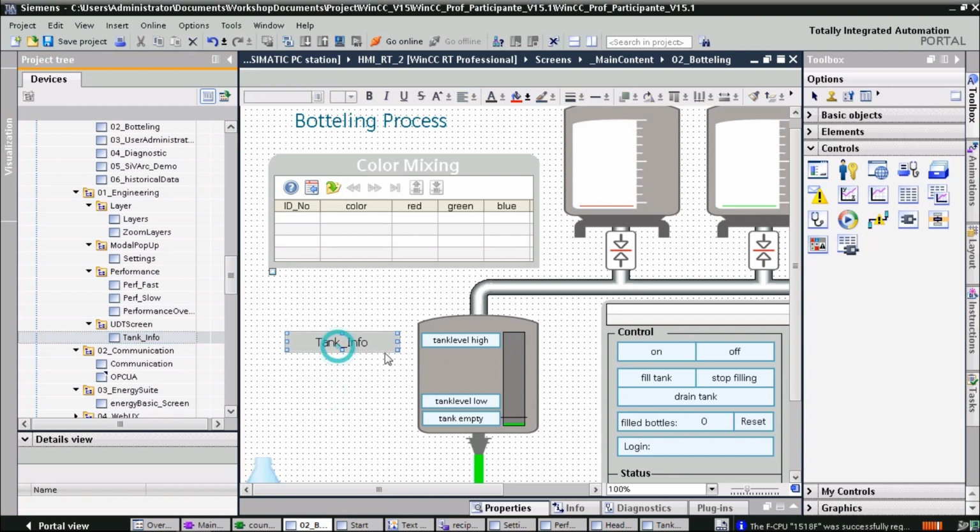So in the case of the red tag, we switch to our UDT, which we've just included before, in our tag info tag table. And for tag red, we do have the color and content, and we are just interested in the tag graphics itself, which is actually the whole tag underline details dot tag underline red. And I'm just going to copy that, go back into my screen, and my tag graphics is now the tag graphics of the red tag.